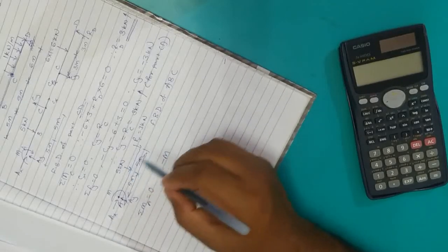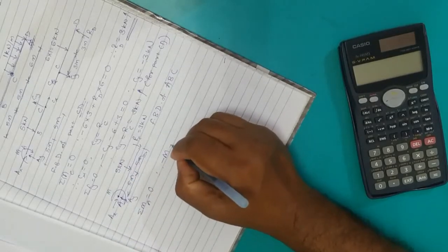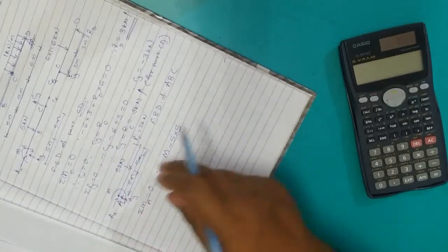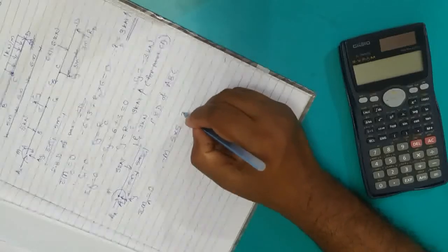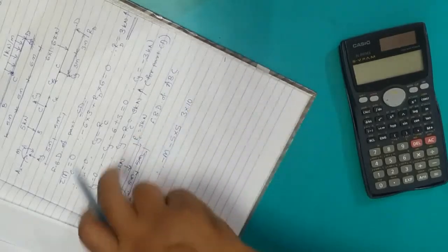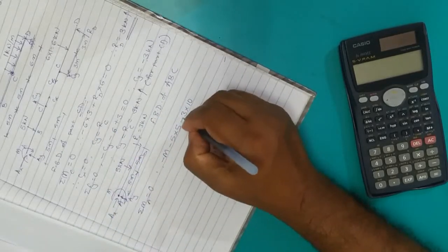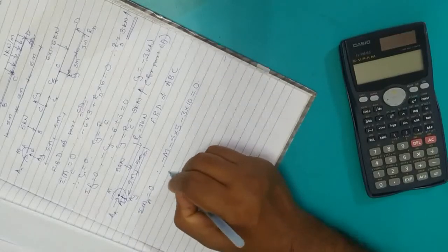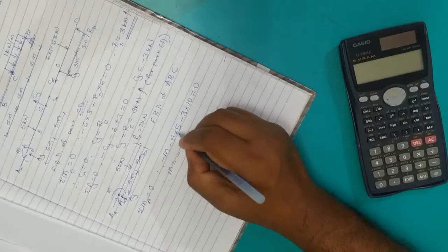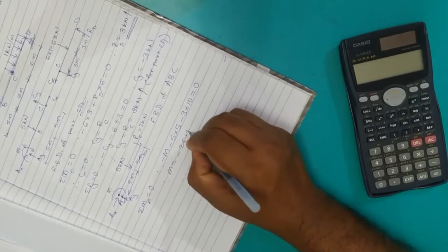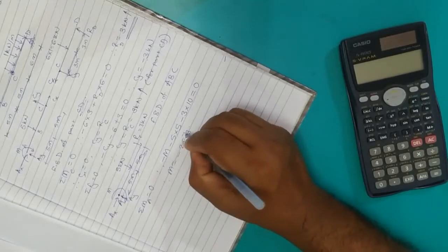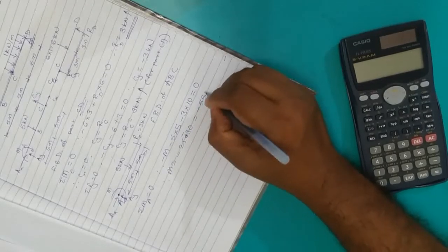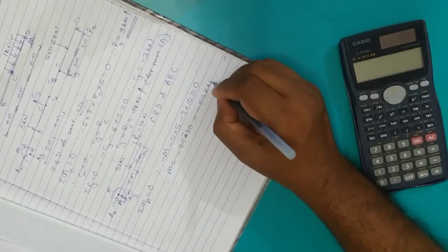Then next, force 5 kilonewton. So minus 5 into 5, minus, because the rotation is going to be clockwise. Here Rc, which is 3 into 10, that rotation is also going to be clockwise, so that should also be negative. So what we have here is M equals minus 25 plus 30, rather that is minus 30, so that will be minus 55 kilonewton meter.